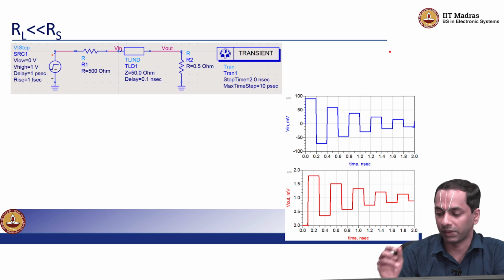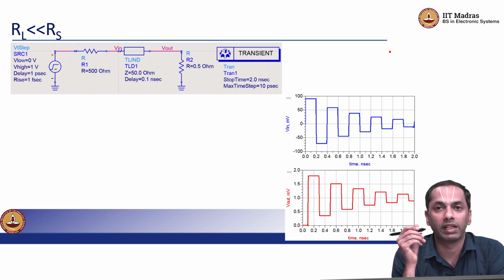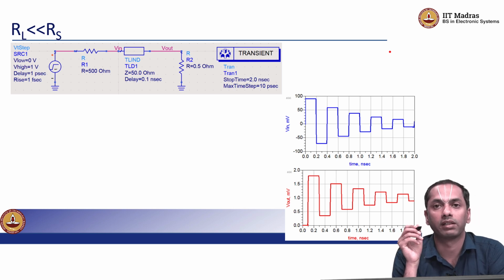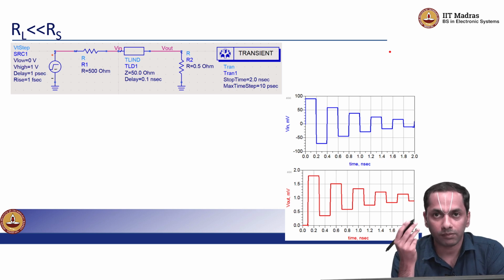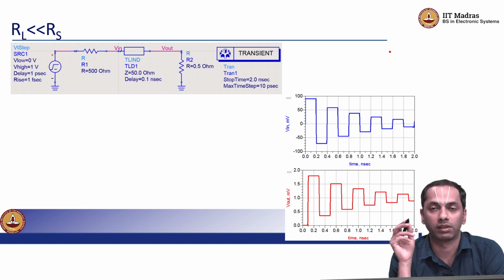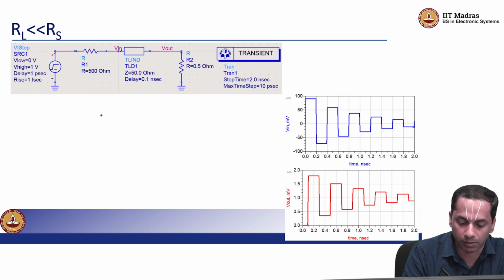So in this case, we essentially want to see where the R, L and C are. This is very reminiscent of an RLC charging. So I need both the inductor and capacitor in this situation. I cannot take away either a capacitor or an inductor. Remember, if I only had R and L or R and C, I will not have a ringing behavior. A ringing behavior is only akin to circuits where I have both an L and a C along with the R. So here, if we take a look at, say, the pi model,